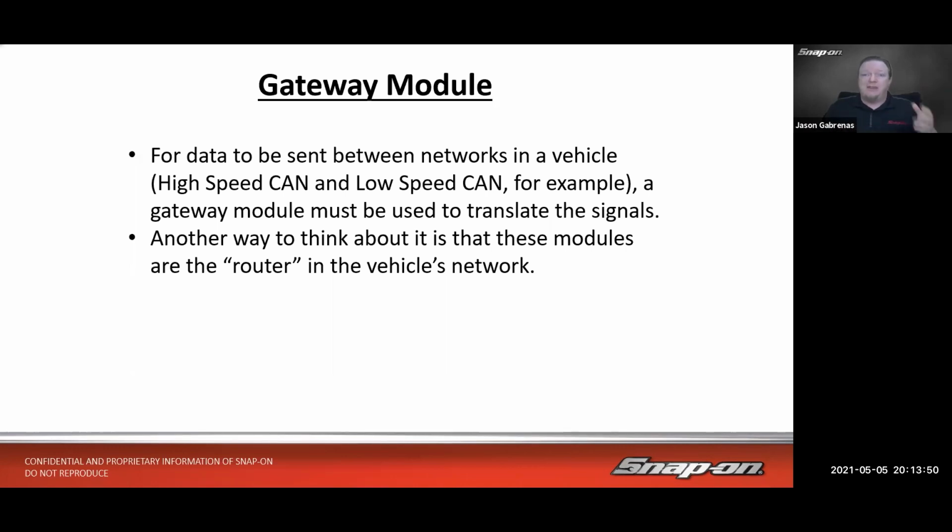So you may have heard of maybe Chrysler's secure gateway module, and that's different. I would think of that more like a firewall for the car. So that doesn't allow outsiders in. You have to be allowed access to get into the vehicle. So they call it a secure gateway module because it is really the gateway to the outside world, but it's not this type of gateway module we're talking about. So the way I think of a gateway module on a vehicle in this sense is it's like the router for your car.